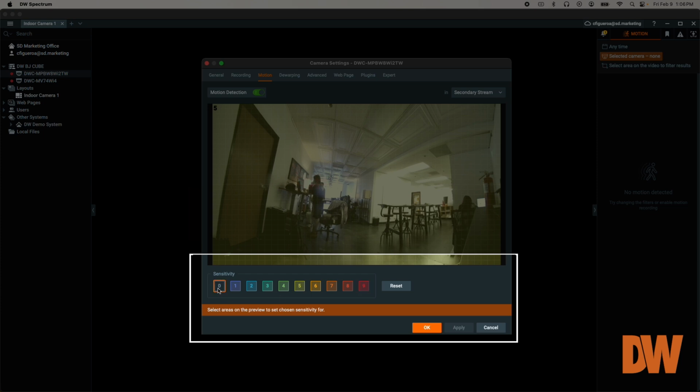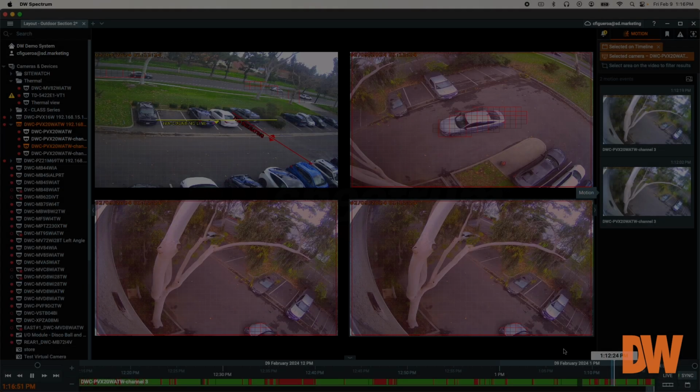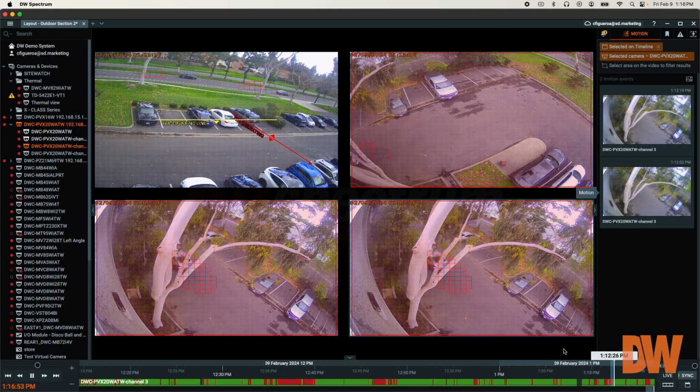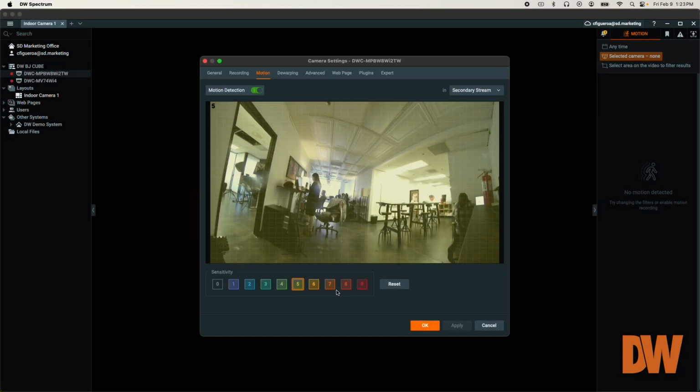A Level 0 sensitivity or low-level sensitivity is best applied to high-traffic areas where false positive detections are most likely to take place. Street-facing cameras, tree and plant foliage, and constant foot traffic are a few example situations that can otherwise trigger false positive motion detection. Click and drag to map the sensitivity in the motion areas. A live stream of the selected camera will display for reference.